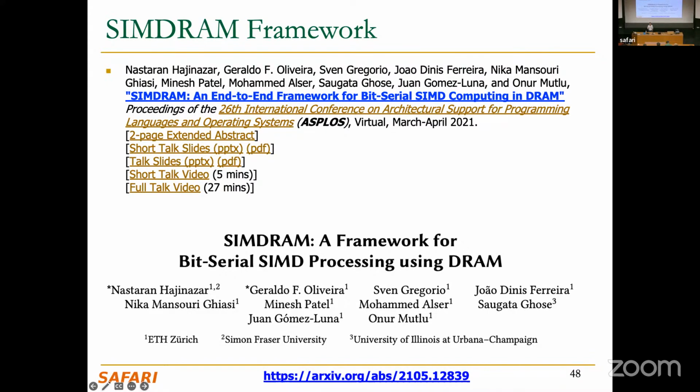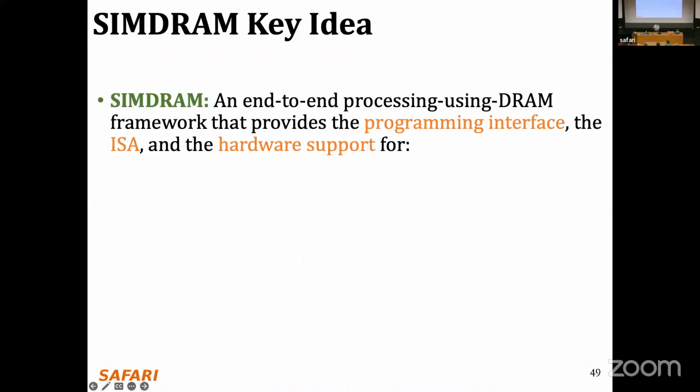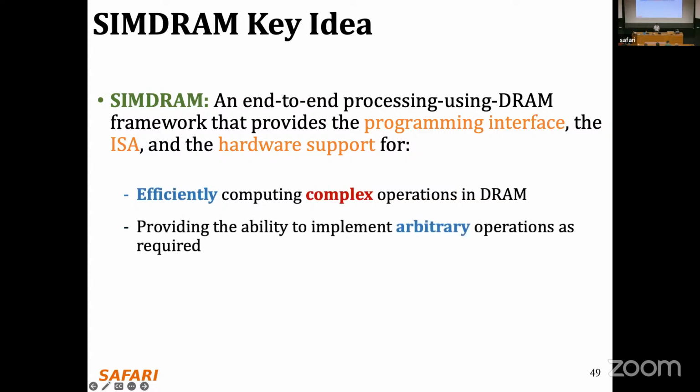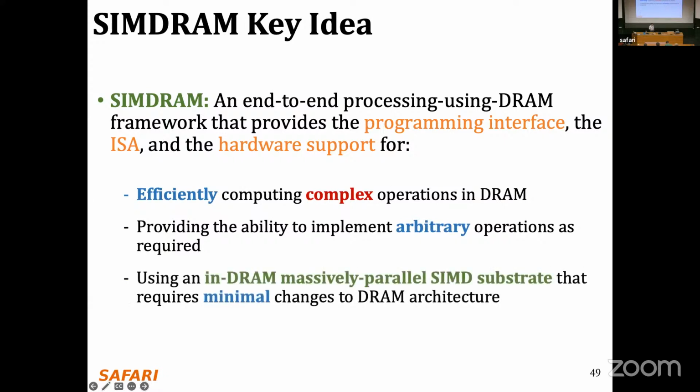these bitwise or Boolean operations, we can implement more complex arithmetic operations using the same ideas of RowCopy and in-DRAM majority operations. This is the work that I led, called SIMDRAM. SIMDRAM is a framework designed to allow the user to input the operation that they want, and the system itself gives the substrate and the system support for that given operation. So it enables the user to implement arbitrary complex operations inside the DRAM chip itself.